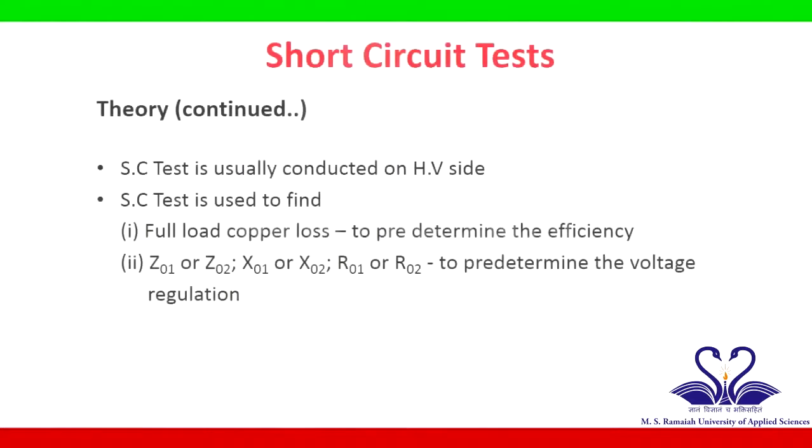Theory of short circuit test. Short circuit test is usually conducted on high voltage side. Short circuit test is used to find full load copper loss, to predetermine the efficiency, Z01 or Z02, X01 or X02, R01 or R02, and to predetermine the voltage regulation.